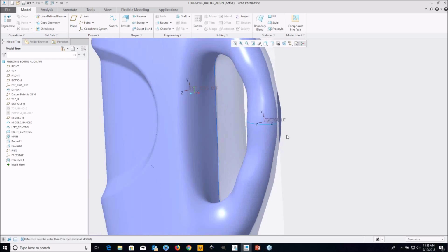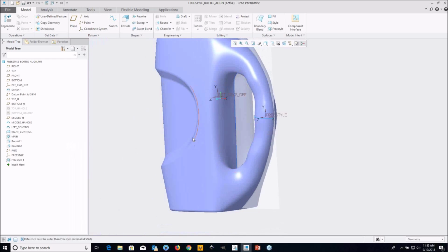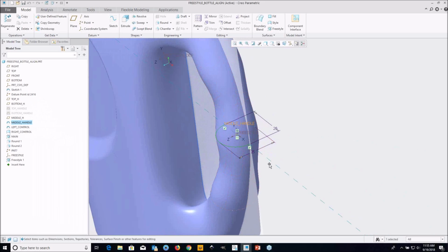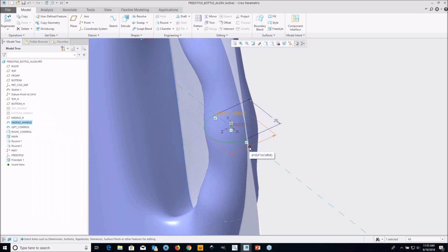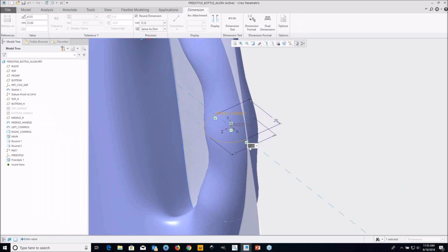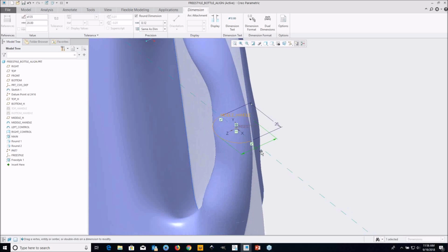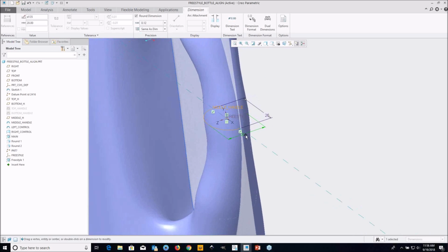So if I select now and I go into that middle handle sketch, because that freestyle mesh is aligned to that sketch, I can come in here now, and if I just change this dimension in that sketch to, let's say, 20, as that sketch redimensions, regenerates, that freestyle mesh also updates with it.